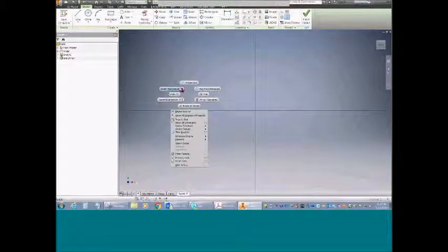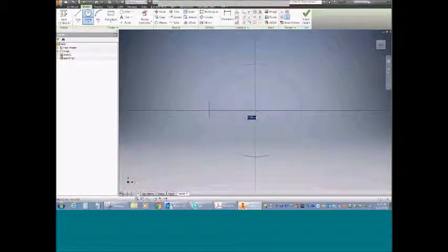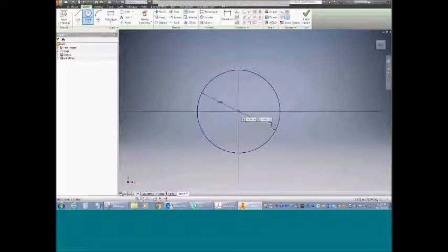So start my sketch here. I'll start off with just a circle. This is going to be the biggest circle on this thing, which is 2 inches in diameter. So that one was real simple. I just locked it down to the origin point, and I knew it was only going to take 1 dimension, no opportunities to create any constraints there. So we're going to finish that one.